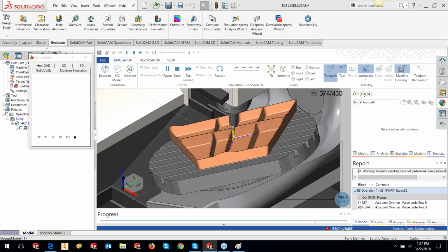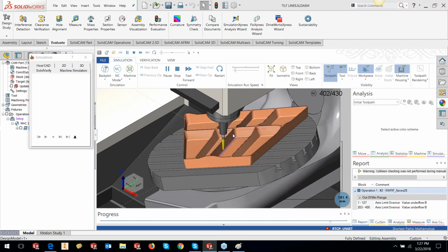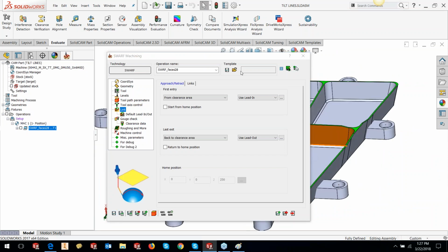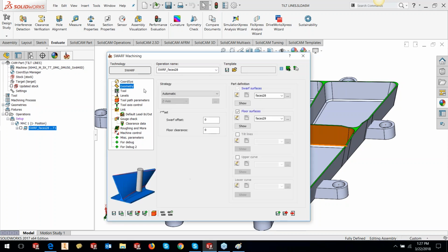So what you can actually do when you encounter such situations where you feel that the rotation is too much and you would like to control how the tool is going to behave in certain areas. Now, this is the most common situation that you will encounter. To avoid it, you can use the tilt lines method rather than automatic, because sometimes, like I said, in automatic, it cannot find the exact 2 points, and when it tries to come close to the result, you will see a lot of rotations happening on the machine.